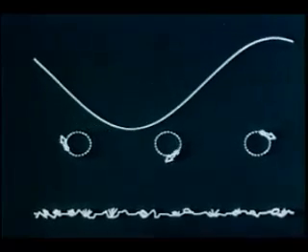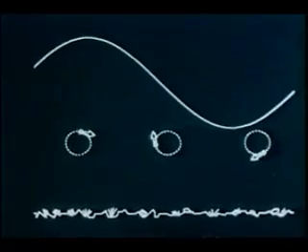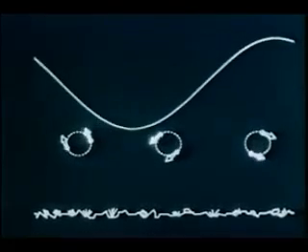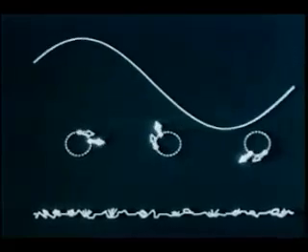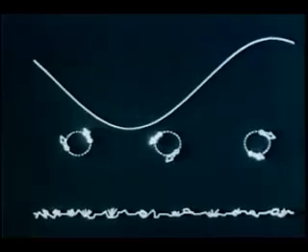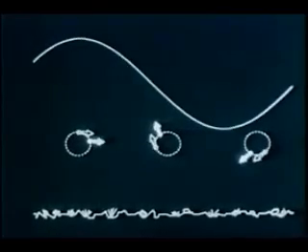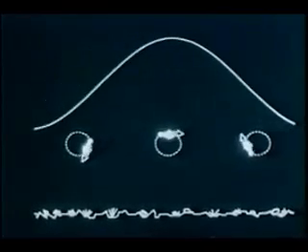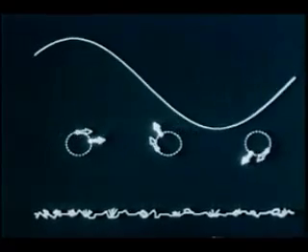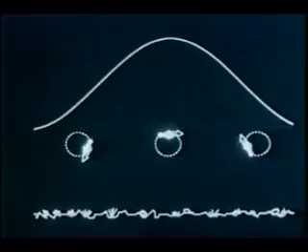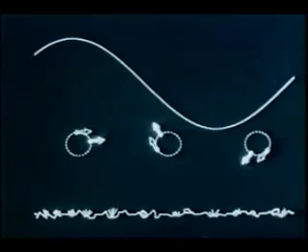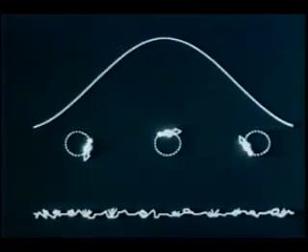Here now is the Eulerian description. In this wave motion, neither the Eulerian nor the Lagrangian description is steady. In fact, they have an identical appearance. In this flow, if we move our frame with the wave speed, the Eulerian pattern will become stationary. Let's do this and indicate the translation velocity by an arrow at the bottom.